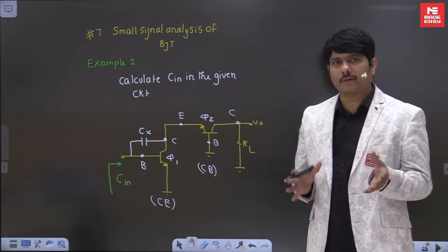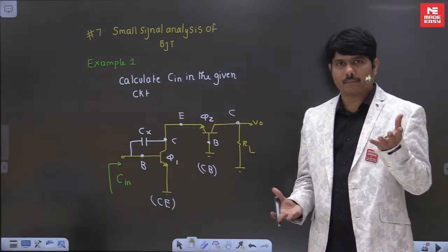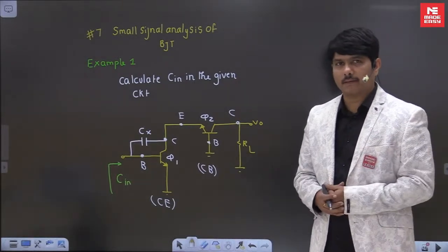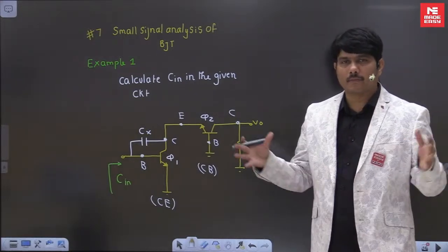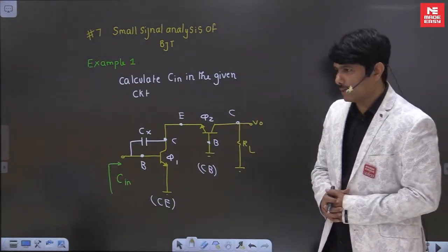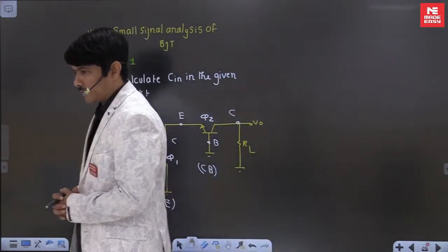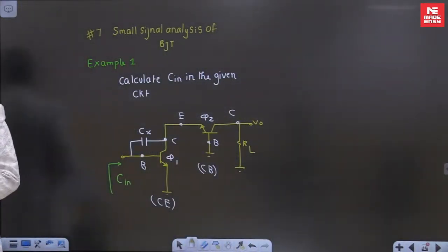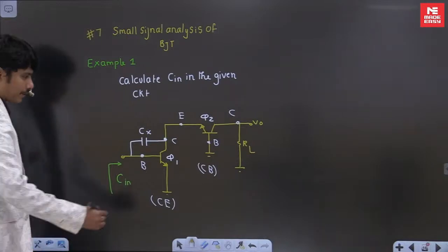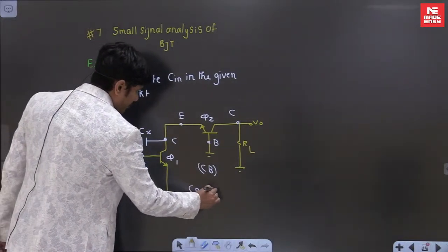which give high gain and high bandwidth at the same time. In general amplifiers, if we get more gain, the bandwidth will be less. If bandwidth is more, the gain will be less. But this is a peculiar circuit which gives both at a time. That's why it has a new technical name, cascode technique. Everybody, I hope you understood. It's a cascode circuit.